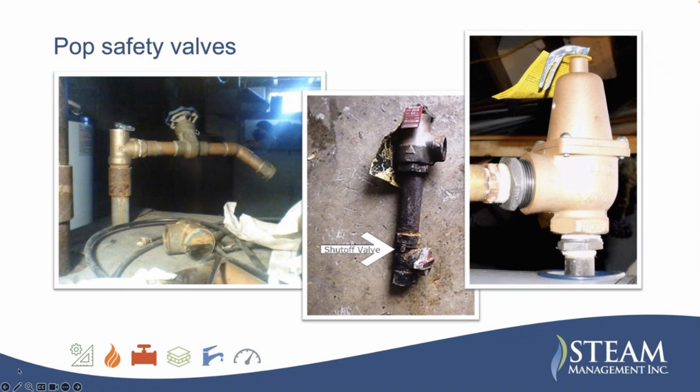Pump safety valves. This one in the center was from an explosion of a boiler, a cast iron boiler that blew up. A friend of mine that was responsible, he was a boiler inspector, sent this to me. And you could see why it failed. This is the last line of defense, and someone decided to install a valve on there, and it was closed.